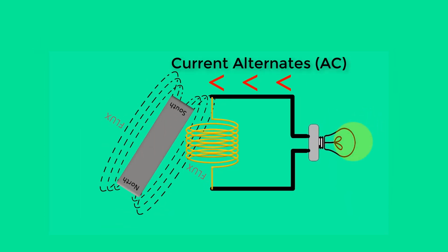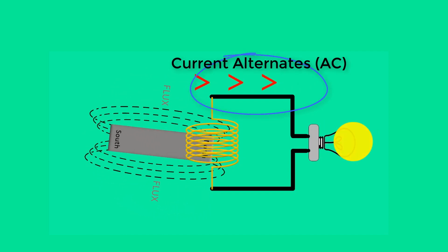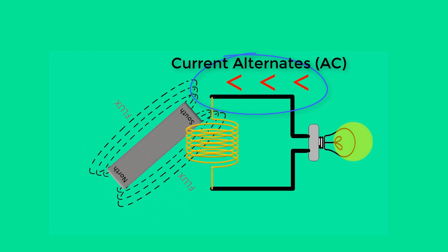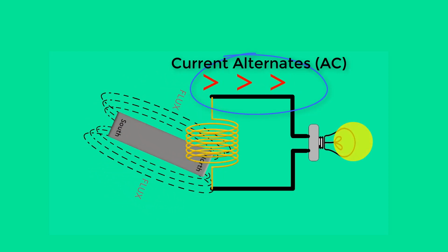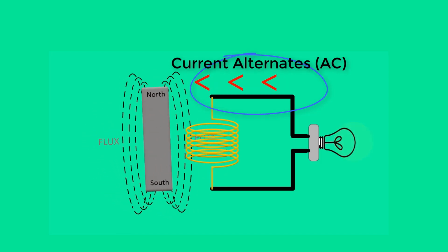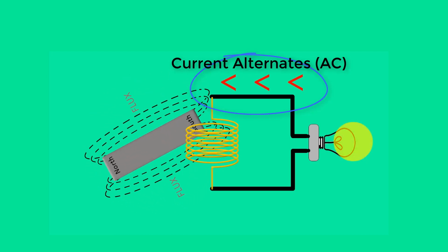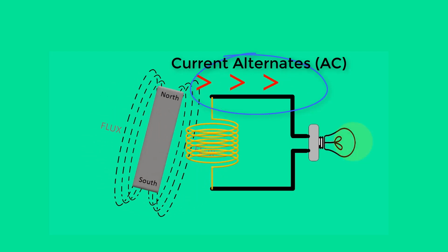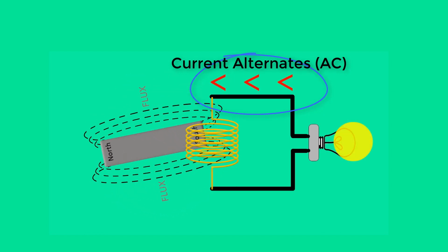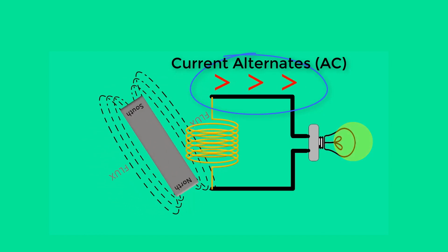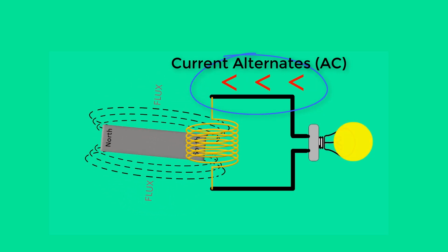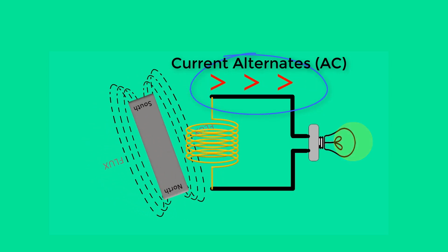In this example, the magnet rotates, creating a current in the circuit. Notice in the example shown here that the current flows in one direction during the first half of the rotation and in the opposite direction on the second half of the rotation. One complete rotation produces a voltage in the circuit that starts at 0 volts, goes to a maximum voltage, returns to 0 volts, and goes to a maximum voltage in the opposite polarity. Let's take a closer look at the voltage that is created.